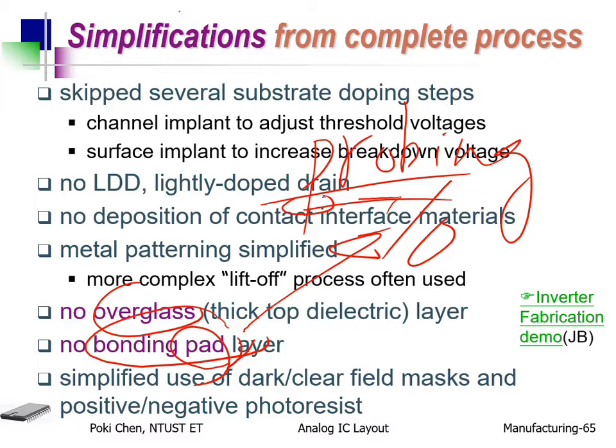However, after testing, all those probing pads won't be connected because they are useless. Only to make sure whether or not the chip is functional. That's it. If it is not functional, just throw it away. Right? If it is functional, then you need to do packaging through the I/O pads. You need to have bonding wire, connect all those I/O pads to the metal pins, to the balls, to the PCB, as you like.